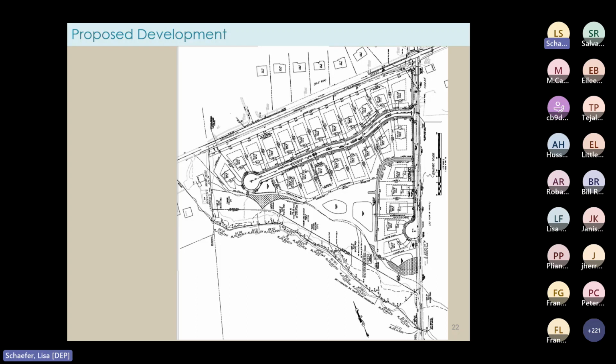The stormwater management report indicated that 4.7 acres of impervious cover is proposed, but it didn't have a breakdown into the motor vehicle surface versus rooftop. Of course, that breakdown is important with the rule amendments.